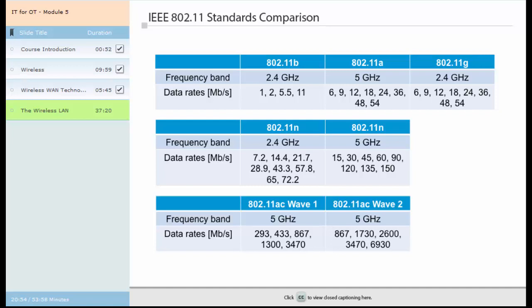Another development by IEEE obtained higher data rates. The IEEE 802.11g amendment uses the newer coding technology for higher speeds, yet is backward compatible with the 802.11b standard using the same 2.4 GHz frequency band. Data rates of 1, 2, 5.5, and 11 megabits per second are supported, as are data rates of 6, 9, 12, 18, 24, 36, 48, and 54 megabits per second.